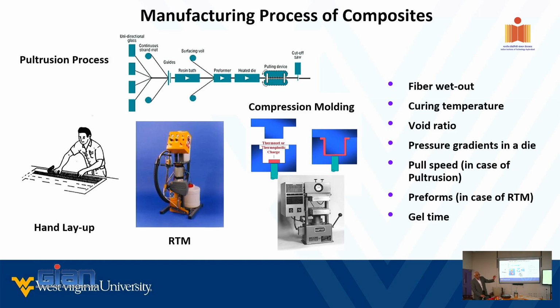Now, theoretically, depending on how you position the fibers, the max volume fraction we can get is 81.3%. That's the absolute limit. You will never achieve that. If you attempt to go to 80% volume fraction with glass, it will never wet out properly.